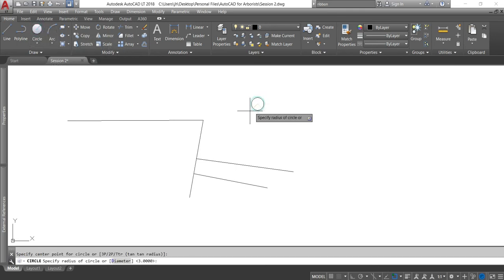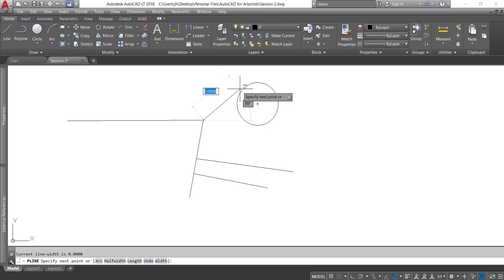If I draw a quick circle, and I want to, for example, draw a line from this corner here, I'm going to snap to the end points. If I want to draw a tangent onto this, then we'll wait for the tangent sign to pop up, and we've drawn a tangent. Again, if we want to draw to the center of that circle, we can draw perpendicular there. But if I approach the green circle, it tells me the center of that element.